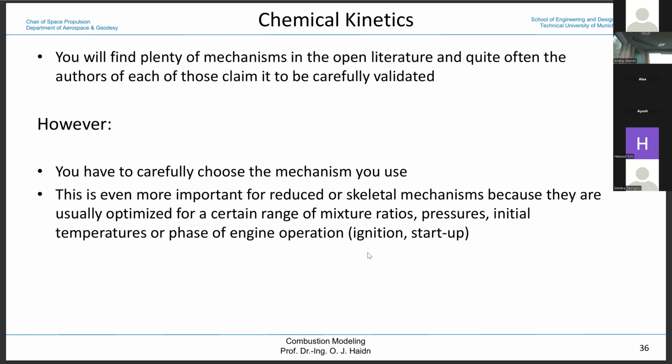We don't do that in the cooling channel, but there is something to do with methane. It could be that, you know, about core methane, but normally liquefied natural gas. You may be in a supercritical state, and now you have energy in the cooling channel, you heat it up. And in a certain mixture, instead of having a gas, since you are already supercritical, one component may condense. So you get a two-phase flow by adding energy to the system, and the supercritical state will always exist. So if you look at a book, it's called retrograde phase change. So retrograde means unexpected phase change.